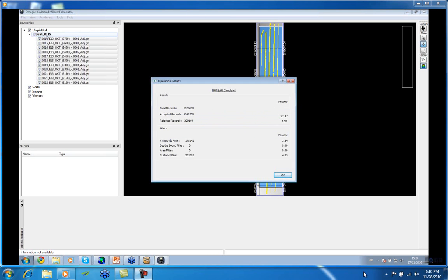What it's doing then is basically trying to establish a grid node from wherever you are down to the equator. If you're on the equator, you're lucky, and then you've probably still got some hard drive space. If you're up in the North Sea, you're unlucky because it's trying to do a 1 meter DTM all the way down to the equator. So it'll basically fill up your hard drive until it stops. So if you see it on initializing bins and it's taking a long time, that's the problem. It's got some flyer in it.